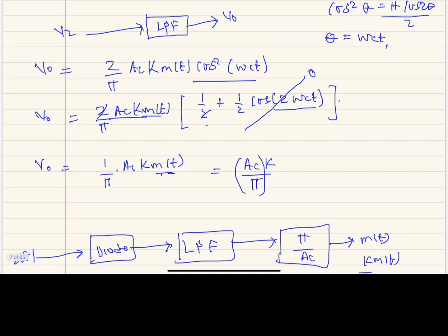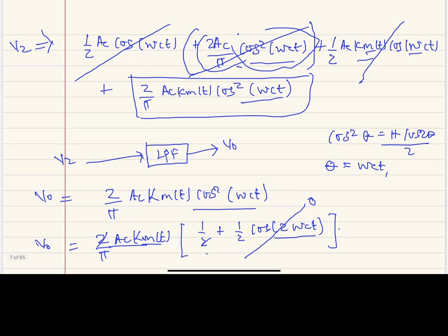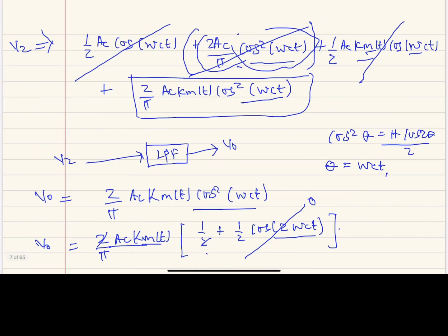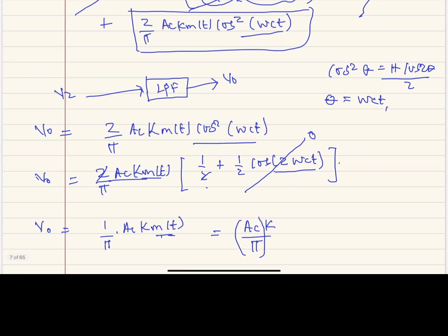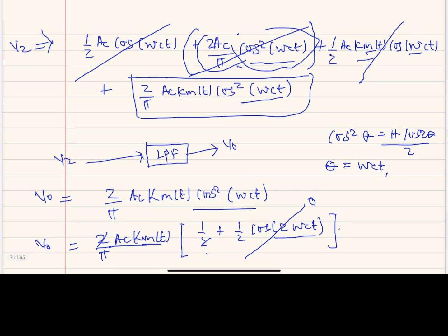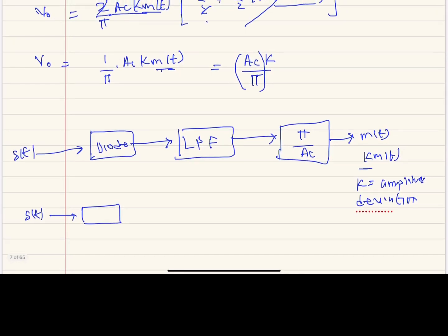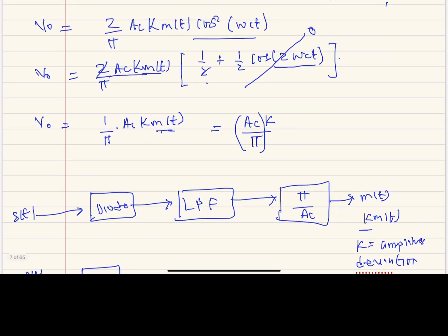The diode will multiply it by a train of pulses, and I showed that train of pulses, it's this one. So when we are done with this, because of the nonlinear nature of the diode, some harmonics will be introduced into the resulting output. And therefore, when we pass it through the low pass filter, it will attenuate all the unwanted frequencies, leaving the lower frequency, which is our desired message signal, to pass.